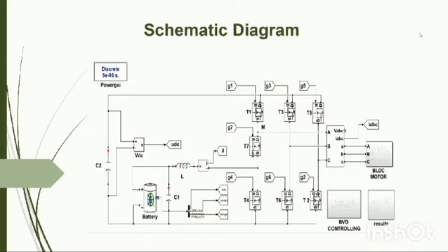Here C1 and L act as filters and avoid ripples, and the switches generate the pulses which are given to the motor. From the motor, the actual speed is measured. From C2, the bus voltage is measured. Gate driving signals are generated based on the switching operation.